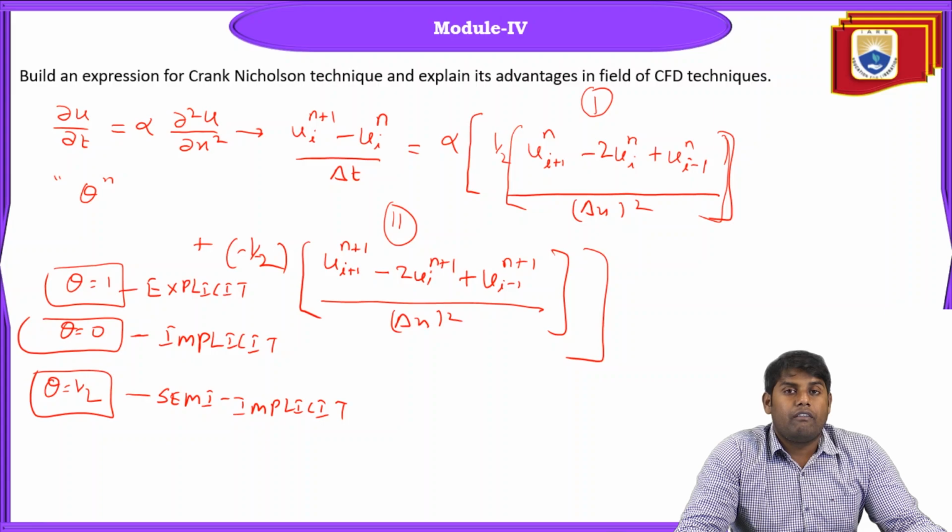Why? Because if you take the explicit method, it is a very straightforward method. The initial value for obtaining the numerical simulation after a run is very straightforward and easy for the explicit method. Whereas for the implicit method, you have to invert the full form of the matrix. So you have to actually do the inversion of the full matrix. Therefore, it is difficult.